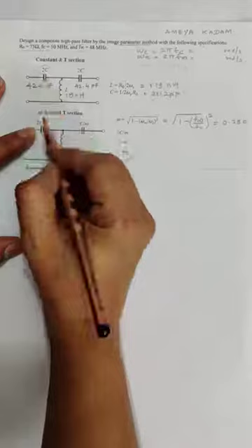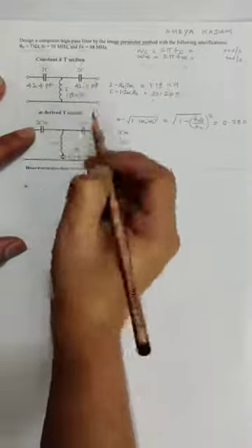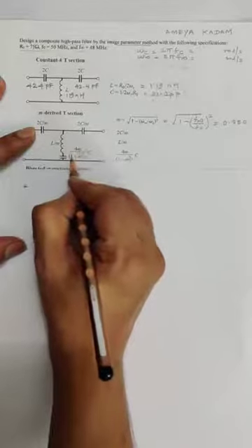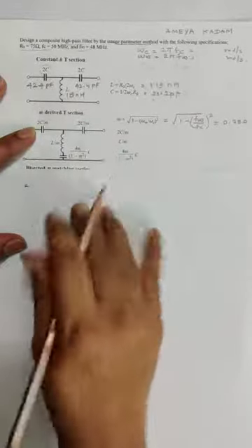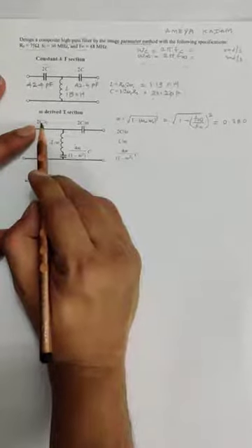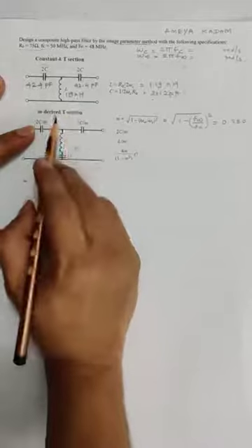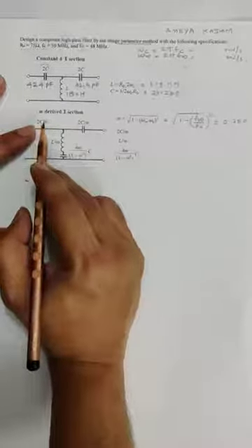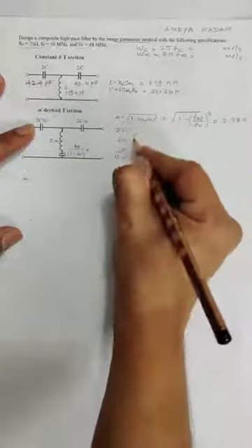So we'll use this M for designing this M derived T section. So the component values are 2C by M, you have L by M, and here it is 4M by 1 minus M square into C. In a high pass filter, M is in the denominator, on the opposite side of the component, while in a low pass filter M is with the component. You can observe this thing. So now we'll calculate these values.